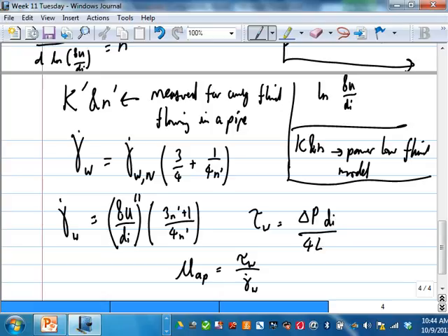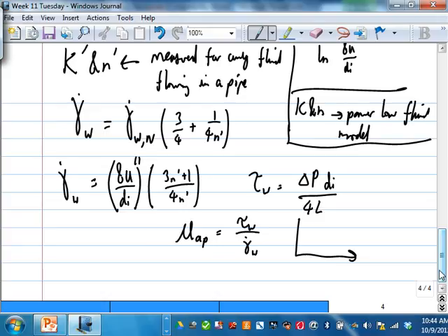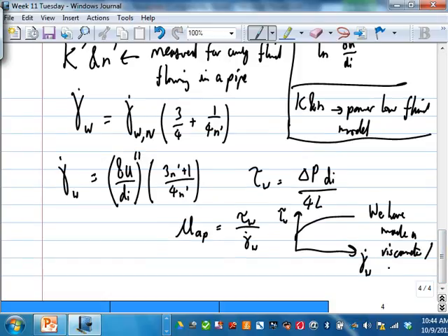Alright? So as we vary the flow rates, we should be able to get a plot, something like this. What was it? Shear stress versus strain rate at the wall. We can get our plot. We have made a viscometer or a simple rheometer. Fantastic, right? Save tens of thousands of ringgit. Yeah?